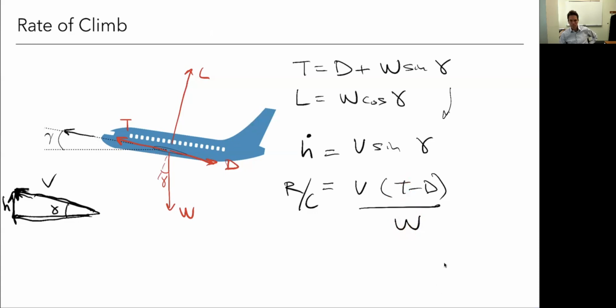So that's important. For electric powered aircraft, the thrust is not constant, but the power is rather constant. And so this quantity here is my input power, right? The force times the velocity, that's power. That's going to be constant. So we talk about power to weight ratio. And you'll remember as we've been designing our electric powered aircraft, we've been talking about guidance on what's a good power to weight ratio. Thrust to weight is less relevant, because thrust varies a lot, but the power to weight is more relevant. So again, that's related to our ability to climb.